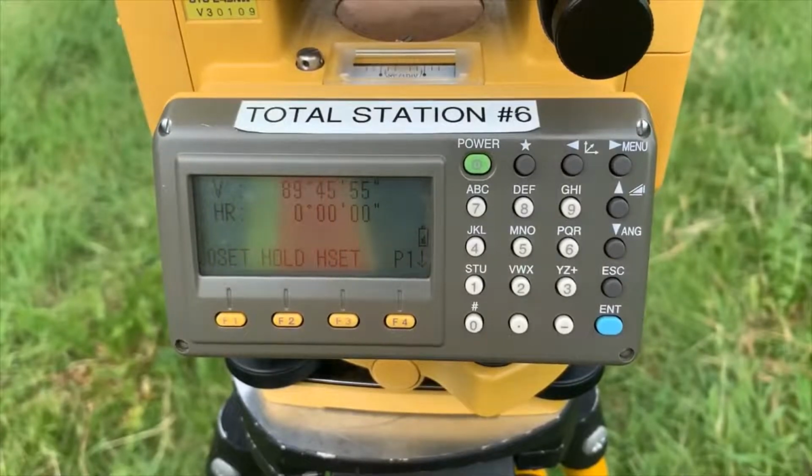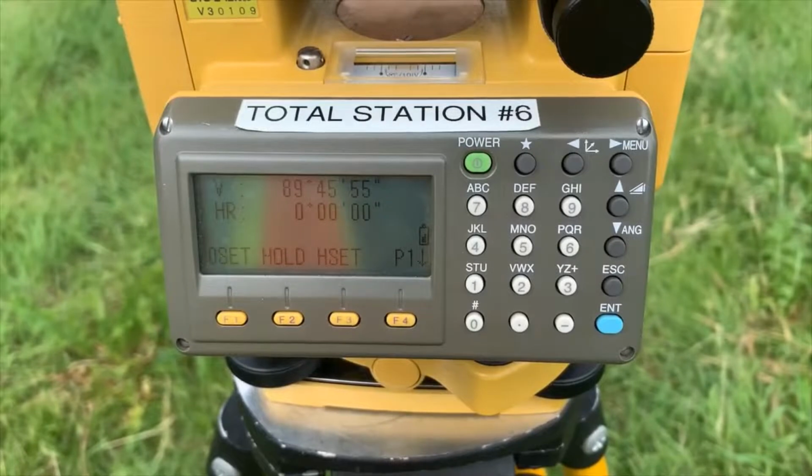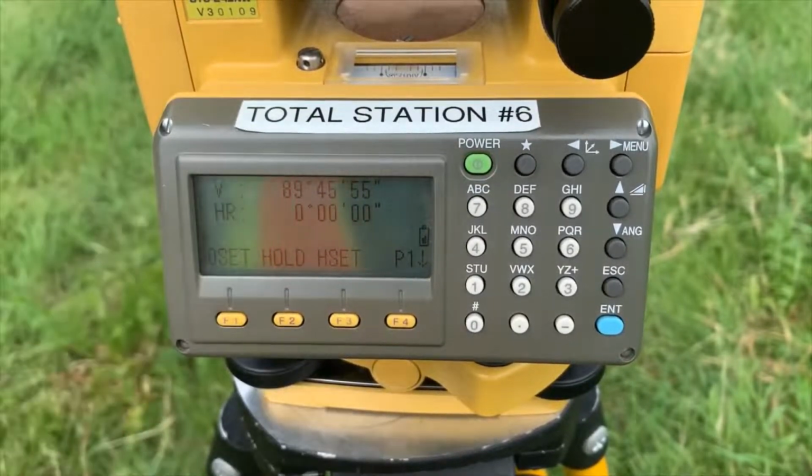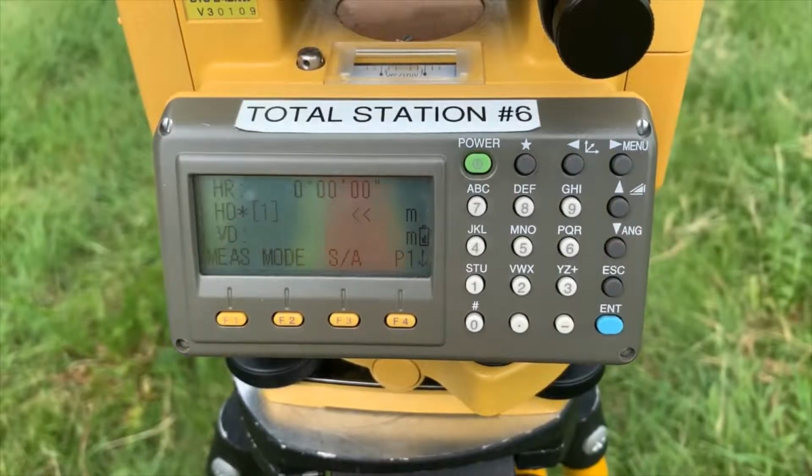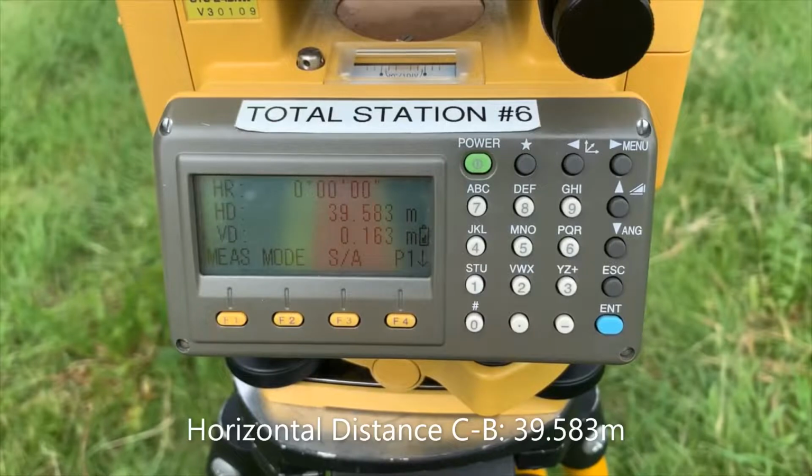Now we've set up our total station over point C6, and we've sighted a prism over B6. We've already zero set our angle. Now we'll take our distance measurement, and our distance from C to B is 39.583 meters.